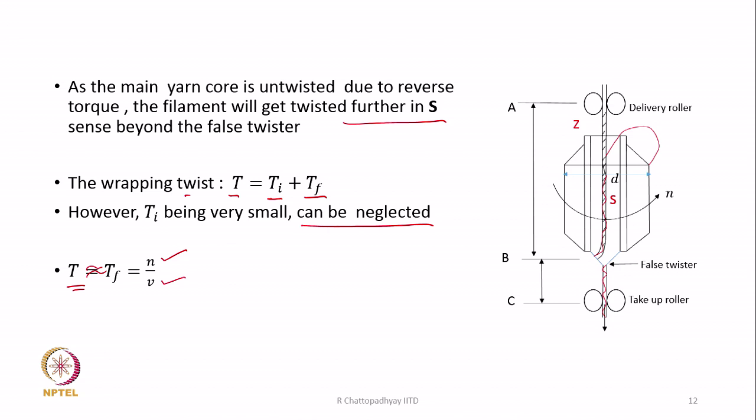The actual twist in ring spun yarn should be the ratio of traveller speed divided by front roll delivery. But the nominal twist we basically calculate on the basis of spindle speed by front roll delivery, though we know that spindle speed and traveller speed are not the same. There is a little difference between these two, and because the difference is there, the yarn is wound around the ring bobbin.